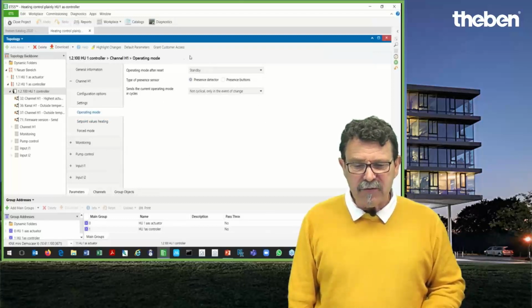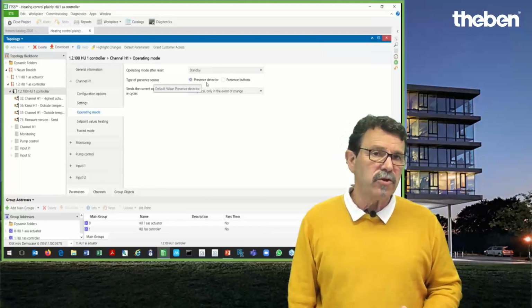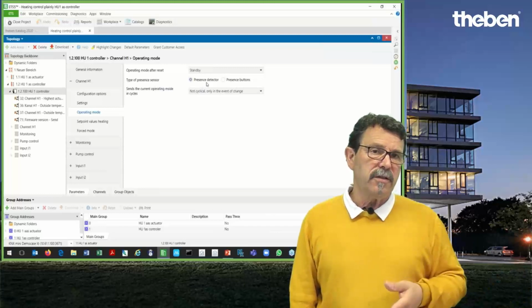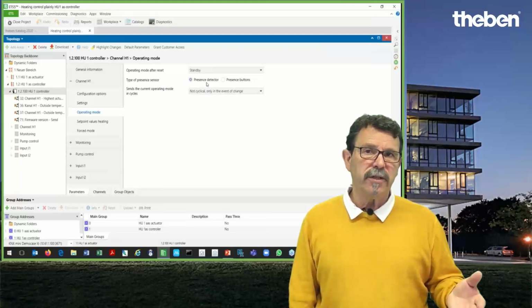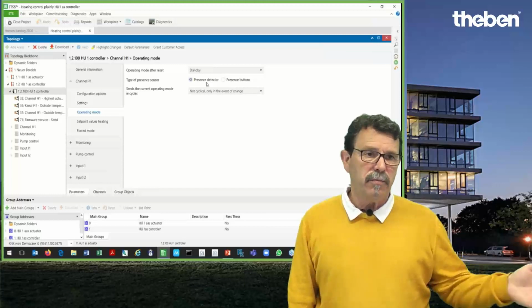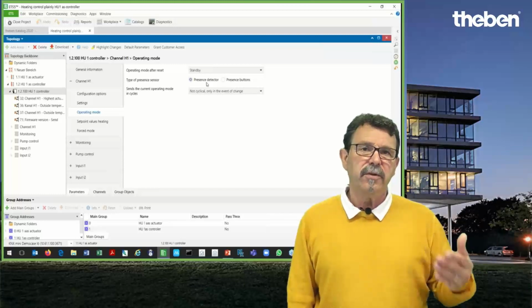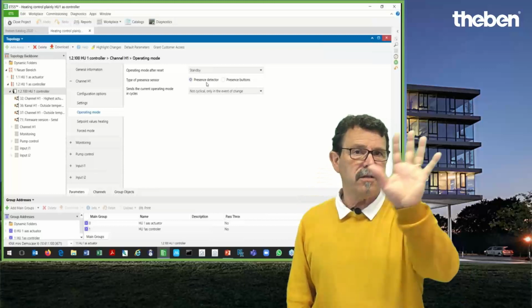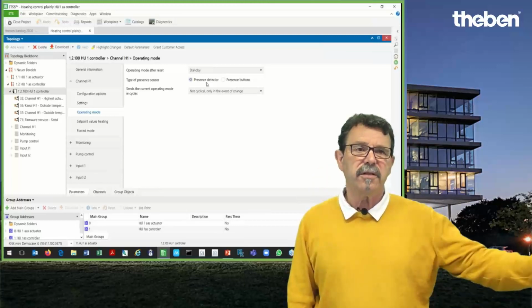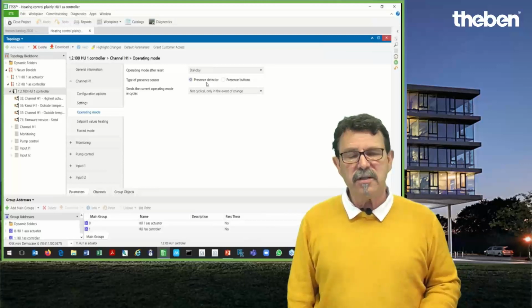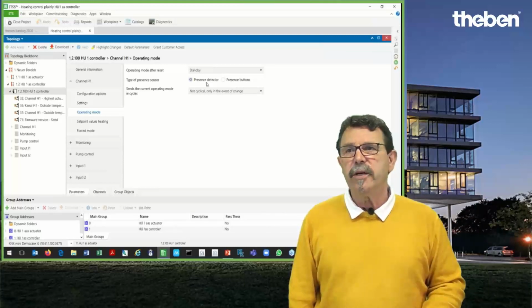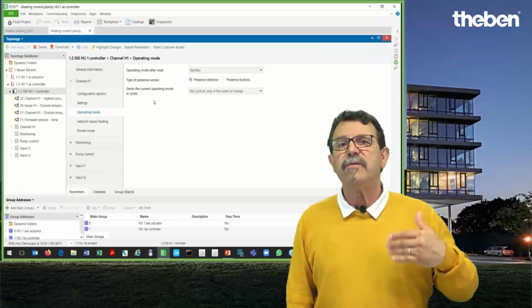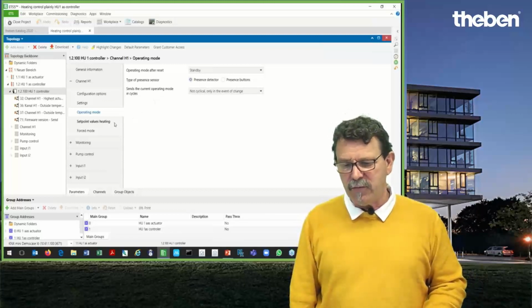Operation mode after reset is more or less standard. You can either use presence sensors to control such a room, if a room is occupied and the presence sensor gives us a reasonable trigger, or you can use a presence button. If a meeting starts, the person who has invited to the meeting, for instance, gives a command on a switch, giving the signal to the outside that the room is blocked, and with the same trigger we address presence: the meeting is ongoing, and we now need the comfort temperature. That means we want it comfortably warm.